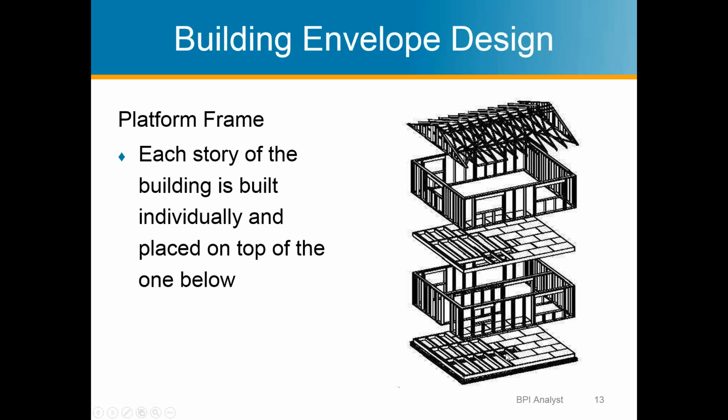So each stud bay is a chimney that's constantly moving air from the crawl space through the wall and up into the attic. And air movement, even if there's some insulation in the walls, air will still move through most types of insulation, and it's going to diminish the effectiveness. A lot of these didn't have any insulation in them. So from a building science perspective, that's probably the biggest concern: we just don't have a draft stop.